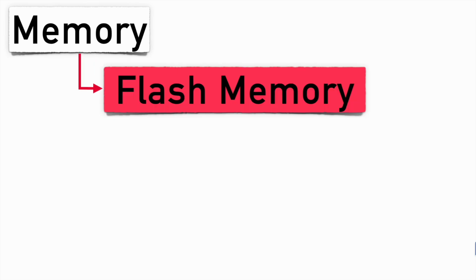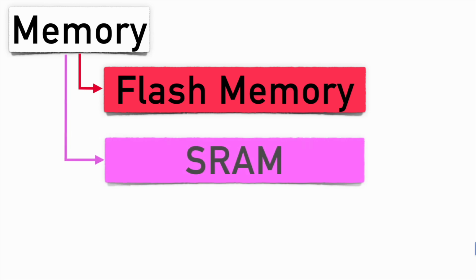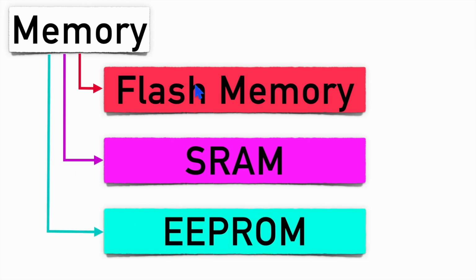What are the different kinds of memory we have in this ATmega microcontroller? If you see the specification, you will find that it has three kinds of memories. The first one is in-system reprogrammable flash memory that can be reprogrammed, the second type of memory that we have is SRAM, and the last one we have is EEPROM. Let's see the flash memory first.